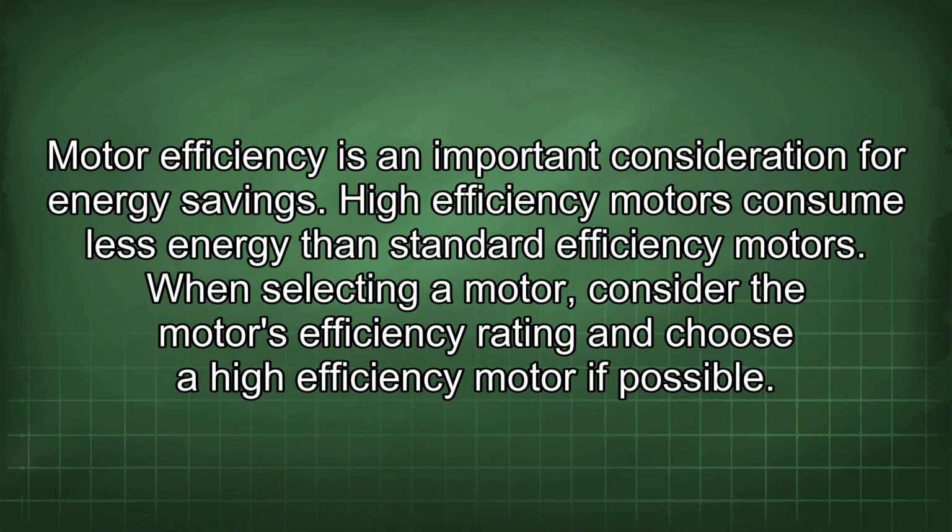Motor efficiency is an important consideration for energy savings. High-efficiency motors consume less energy than standard efficiency motors. When selecting a motor, consider the motor's efficiency rating and choose a high-efficiency motor if possible.